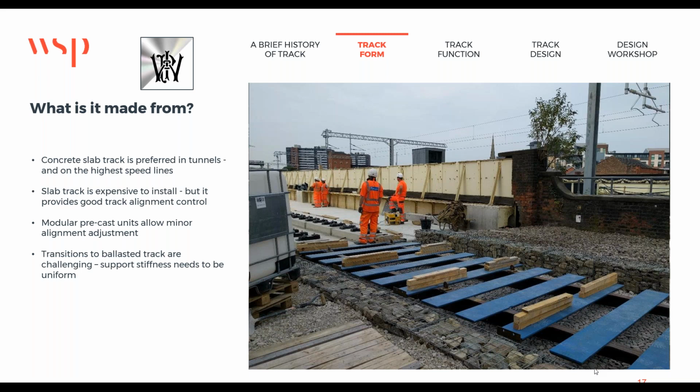So that's why, in terms of the track technology, we need to control twist. Where we have designed twist in our transition spirals, where we apply the cant from straight to curve, it is kept at 1 in 500. That's to make sure that, if that starts to go off, maybe during construction tolerances or track degradation in service, we don't stray into steeper than 1 in 200 and, God forbid, steeper than 1 in 100, and actually start to encourage twist. Hope that answered the question.